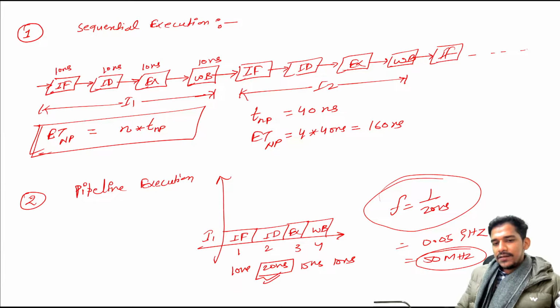So we know that in the first cycle we are fetching the instruction I1. In the second cycle we are decoding the instruction. Because in the second cycle the instruction fetch unit is free, we are not doing any operation on the memory, we are decoding the instruction I1. So what we can do is, in parallel we can start fetching the instruction I2, right?